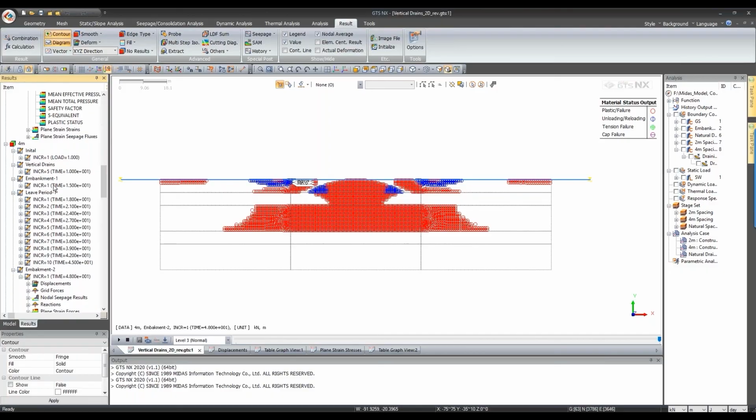And you can find the plastic status differing in 2 meter spacing and natural drainage condition, because more settlement means the soil is reaching its plastic zone, and more difference in the zonal elements. The same model will be given to you for a task, so you can find the plastic status changes as well. So that's up to you.